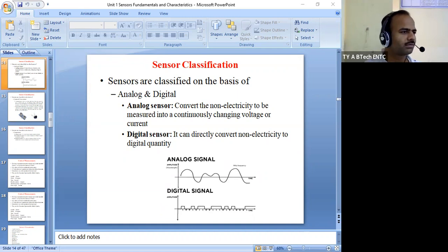So calibration is not required in the sense that it directly interacts with that physical quantity, physical parameter. That's why it will be measuring directly, no issue. But for non-contact type, we have to identify the sensing capability, or response time, of that particular sensor. If the conveyor belt speed is high and the capturing speed of that object detection sensor is low, then instead of counting 2 bottles, your sensor may count only 1, if the response time of that sensor is long.